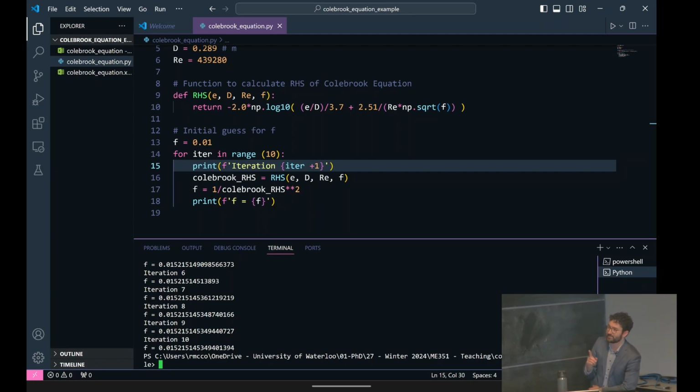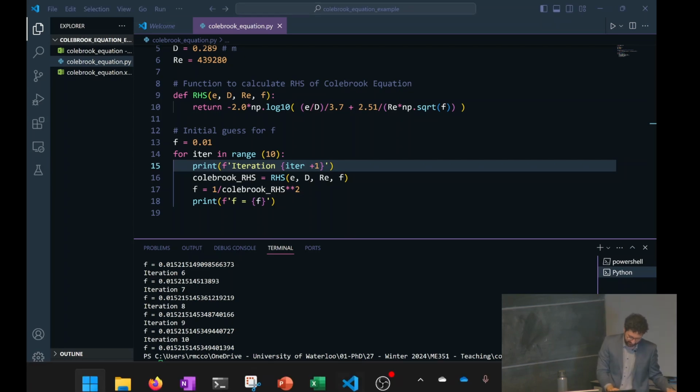Very good questions. Elbows, T's, that sort of thing. You'll notice those aren't in this equation, so we're doing that on Wednesday. Those are called minor losses. The piping system is kind of made out of different, you could think of them as Lego bricks. You have your long pipe, then a valve, then a long pipe, then a bend. So those are different Lego bricks, and we're going to learn how to calculate the pressure drop for each of those components, and then combine that all together to do a system analysis.